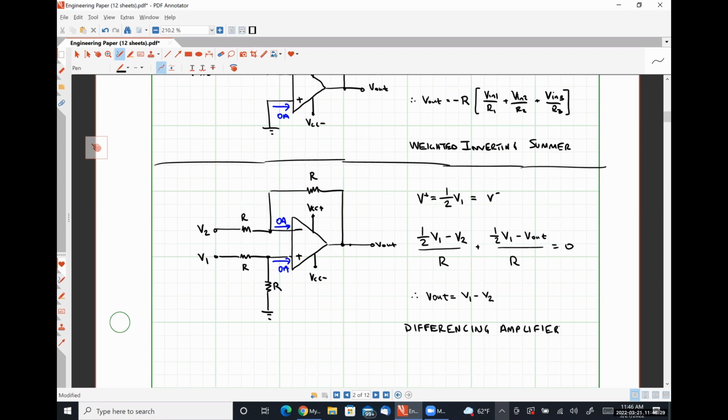So to make V1 larger, the most obvious thing to do would be to have V1 go through an amplifier with a gain of 3 and chain that to be here, as opposed to trying to do it with these resistor values.